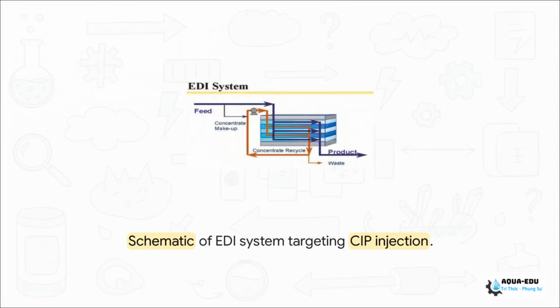Looking at the system flow diagram here, you can see exactly how the cure gets applied. The CIP chemicals have to be carefully, deliberately circulated through both the feed and the concentrate channels. You're using a low pH acid wash to dissolve those insulating calcium carbonate layers. But it requires precision. Too aggressive and you'll permanently fry those delicate ion-selective membranes. You are just trying to dissolve the insulators so your DC current can flow freely once again.